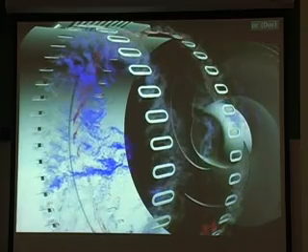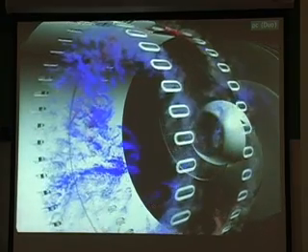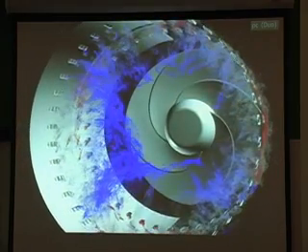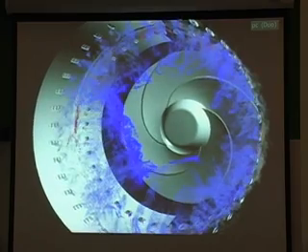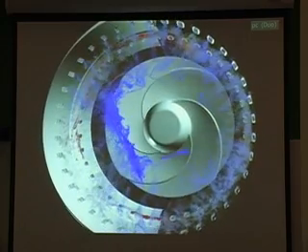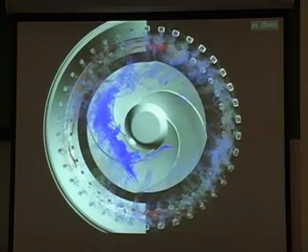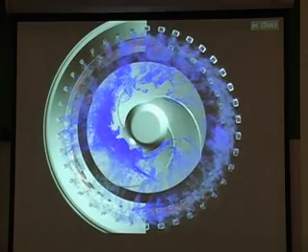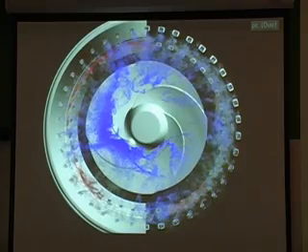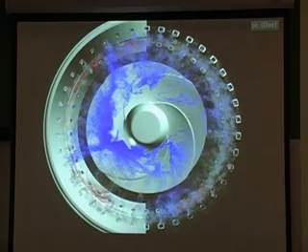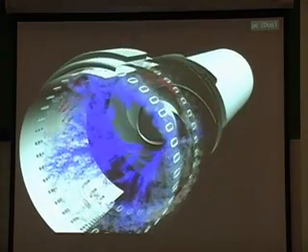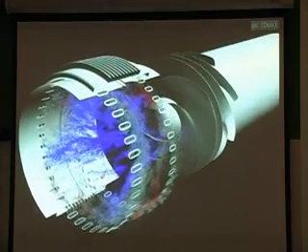The color coding you see, what we're doing here is seeding particles into the flow and advecting them. These are massless particles, so they're showing the direction of the flow. The flow is, now it's away from us, it's toward that impeller. The blue color signifies flow in the correct direction, it's going downstream, and red signifies backflow. And in general you can see that the impeller kind of pulls the flow forward and in. And you can see around the outside we get reverse flow.